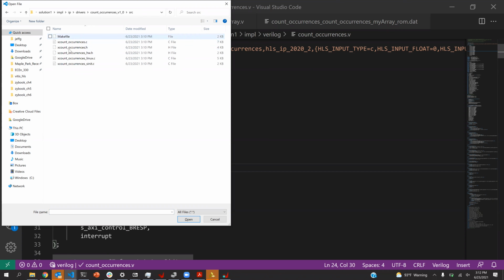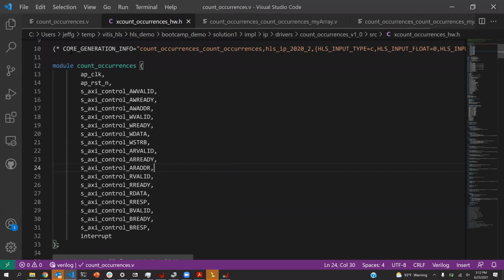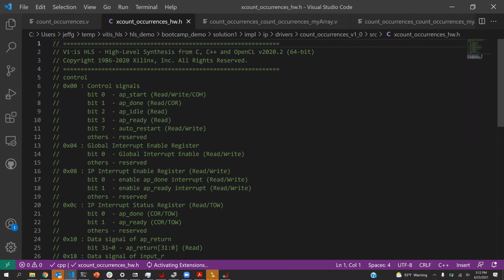Okay, so it makes a few files for this driver. One, this is Xilinx convention, this _HW, is the low-level hardware interface. And there's no PDF document that Xilinx produces for this hardware that tells you the register map because you just made this hardware, okay? So this is the document they print out for you.